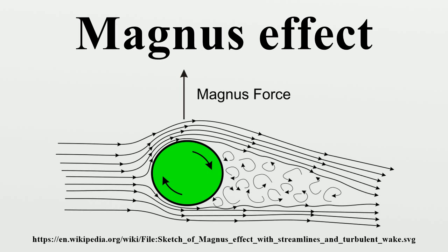The diagram at the head of this article shows lift being produced on a back-spinning ball. The wake and trailing airflow have been deflected downwards. The boundary layer motion is more violent at the underside of the ball, where the spinning movement of the ball's surface is forward and reinforces the effect of the ball's translational movement. The boundary layer generates wake turbulence after a short interval.